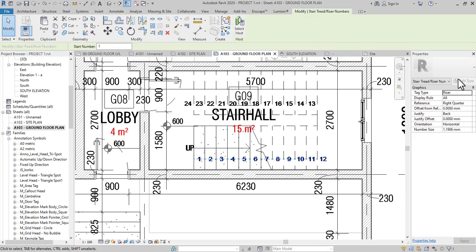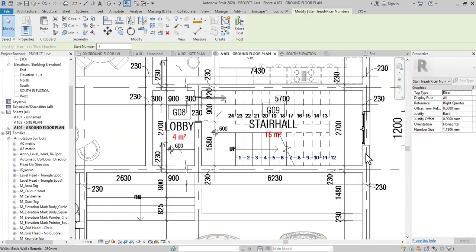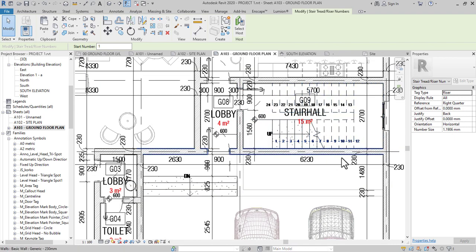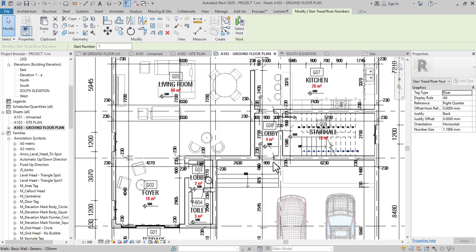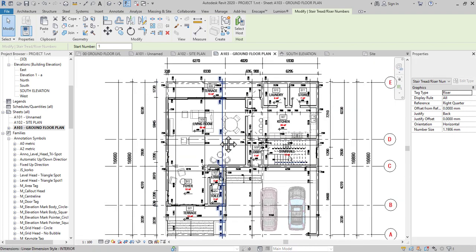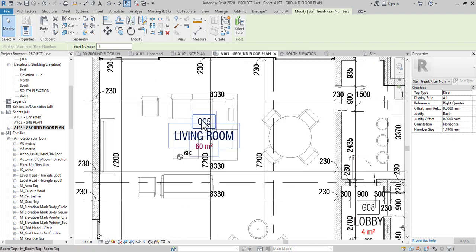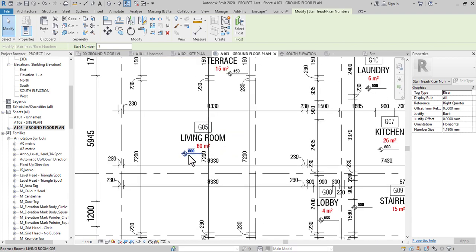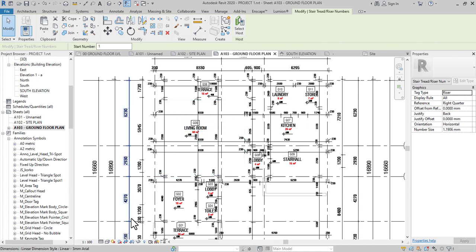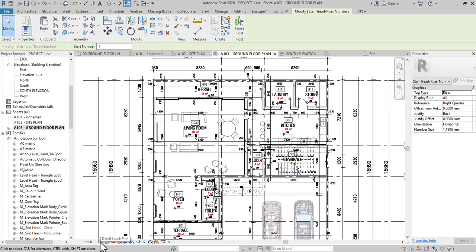So important thing, the first thing you should look at is your room name. So that's quite bigger. So this text is bigger than this, and this is bigger than this, your area, and it's bigger than your spot height. Your furniture is in place, your windows is in place. Also, make sure you put your detail level to fine. So that's where you get all these crisp details from your doors and your windows, your furnitures and stuff. It gives you that added layer of detail.